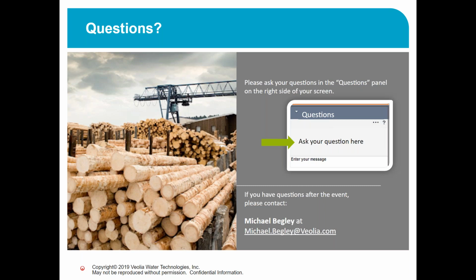You have to take a very large purge based on the potassium to purge the potassium. So this ECRP allows us to make a difference. On some mills, you have maybe a difference of 1 or 2% in sodium recovery. On other mills, we might be at 95% with an ECRP, where we're limited to 70 or 80% with a conventional unit. And between that and the size of the system will let us know whether or not it makes sense.